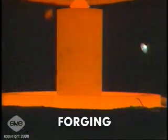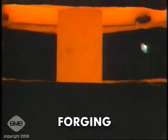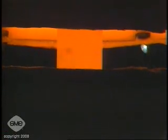Forging refers to hot forming a preform that has been partially shaped and densified by mechanical pressing or sometimes isostatic pressing. Forging can provide both vertical and lateral metal deformation. It is used to increase density and provide more complex or net shapes than can be achieved by mechanical pressing and sintering alone. Density can approach full or theoretical density. Forging can also refine a part's grain structure, improving its structural performance.